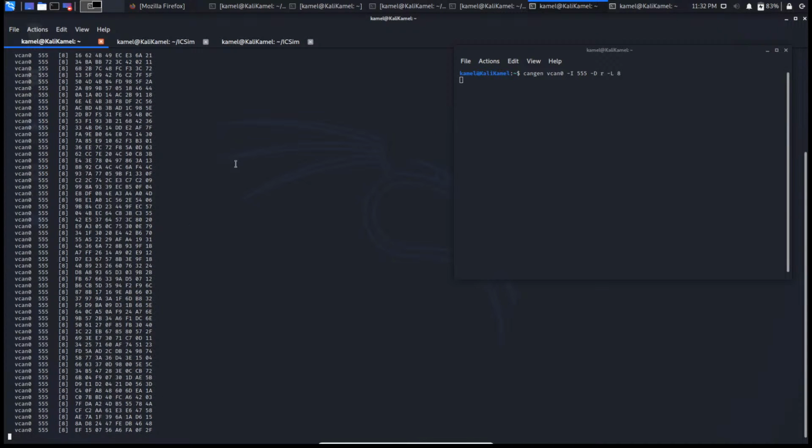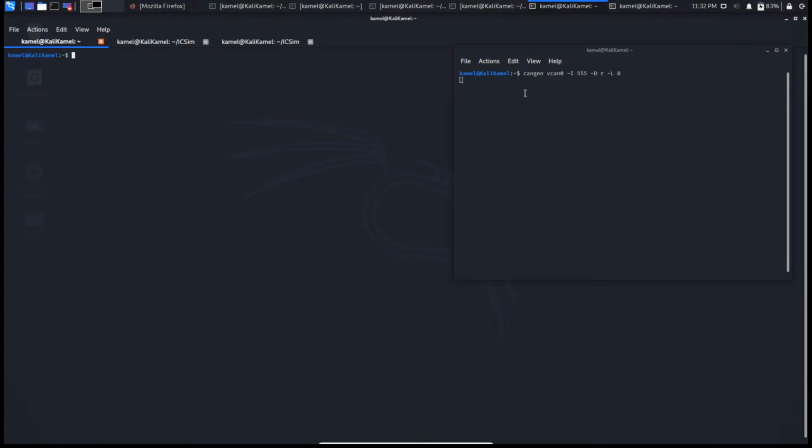But obviously, if you are looking at an actual car, looking at the CAN data like this can be kind of miserable because it's showing you every single message one after the other in a sequential order. If you don't have any filters, your terminal is going to end up filling up very quickly, and it's not really great for doing real-time analysis. It's not really great for what we call reverse engineering. Well, luckily, we have another tool in CANutils specifically made for viewing CAN data with additional information for reverse engineering. And I'm going to talk about that in just a second.